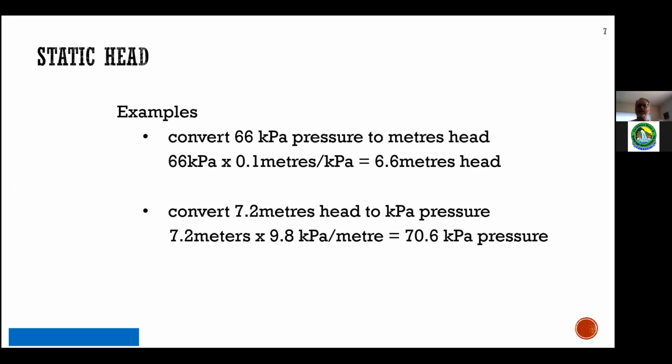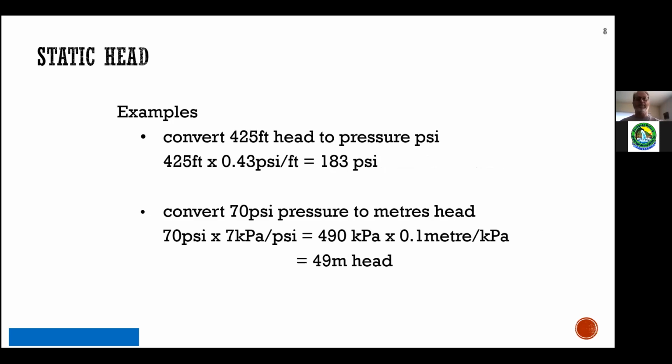You could close a valve that you're not supposed to. You could, or throttle a valve, don't completely close it. So now the supply is restricted, the velocity increases, and the energy decreases. So it's a good way of understanding how the energy in your system not only is created, but how it's delivered. And these are just examples of that.